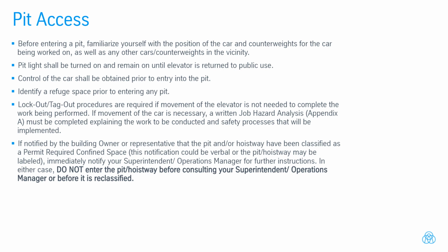Lockout/tagout procedures are required if movement of the elevator is not needed to complete the work being performed. If movement of the car is necessary, a written job hazard analysis, Appendix A, must be completed explaining the work to be conducted and safety processes that will be implemented.